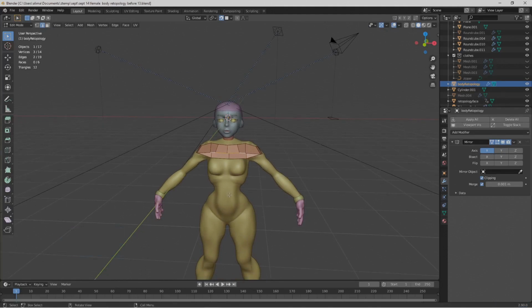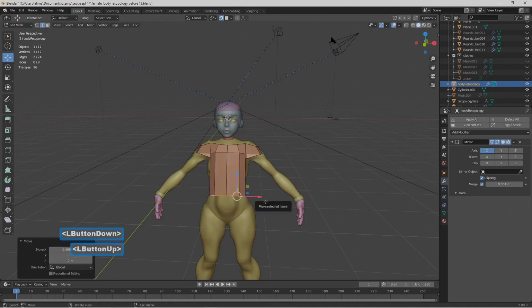With those two pieces selected, typically when I'm about to use control to extrude down, I'll move purposely away from the center, just because sometimes the center can cause me issues. So I'm moving my mouse slightly to the side. I'm now holding control. I'm then going to right click. Okay, so we see the geometry crossed over, which I don't like. I'm going to go to the move tool to pull to the side. There we go. Okay, so now we have most of the upper torso covered.